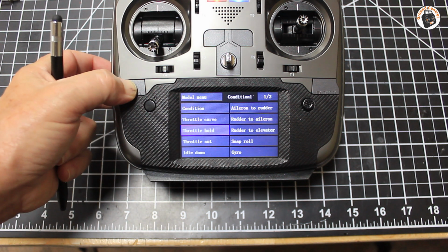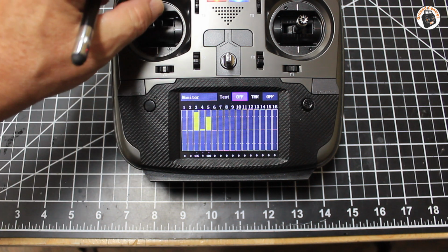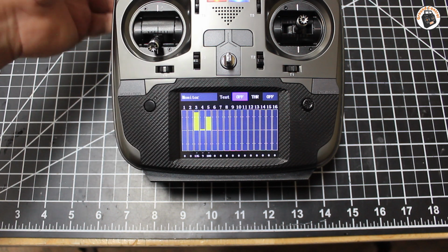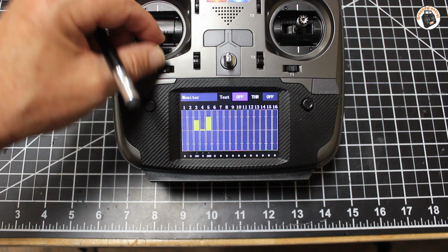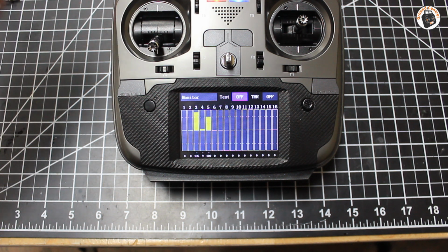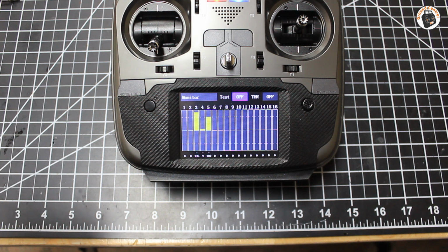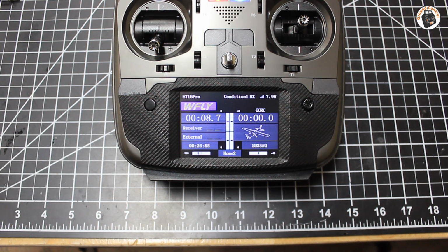All right, let's go to our monitor. So now the throttle is not active. Throttle hold off. When I take off my throttle safety switch, it is active. -100, plus 100. Throttle hold on. All right, I think that's going to work great. So at this point in time, we've done everything I think that we need to do. I think the only thing that we have left to do now is to bind up to it, make sure everything is working, make sure that our